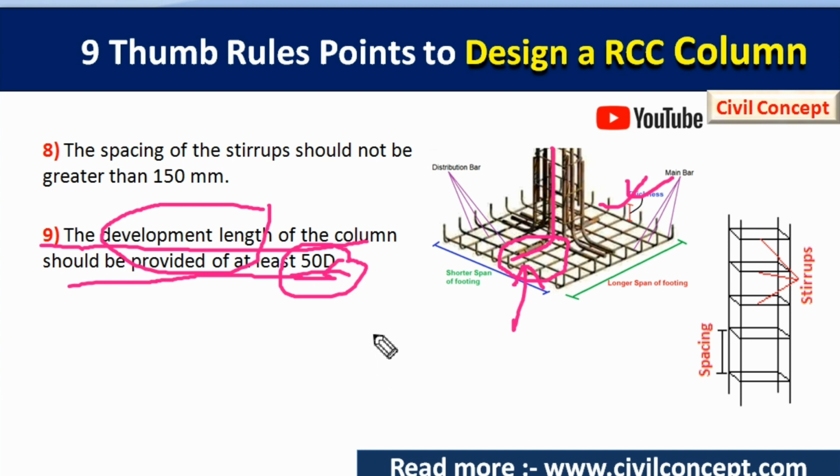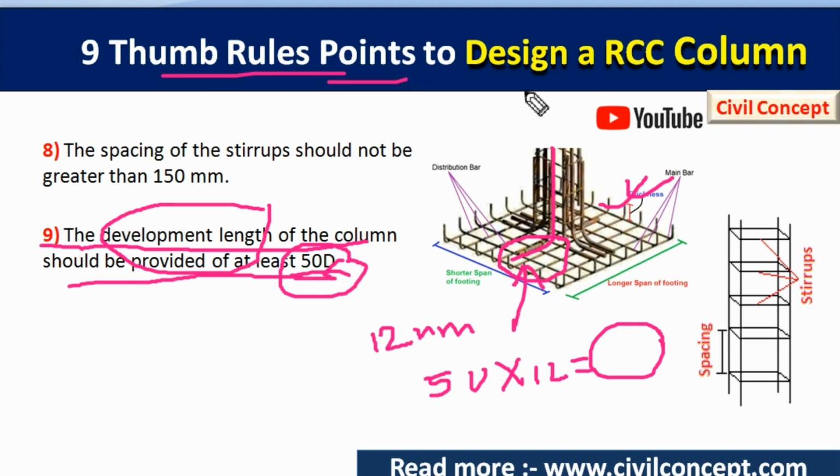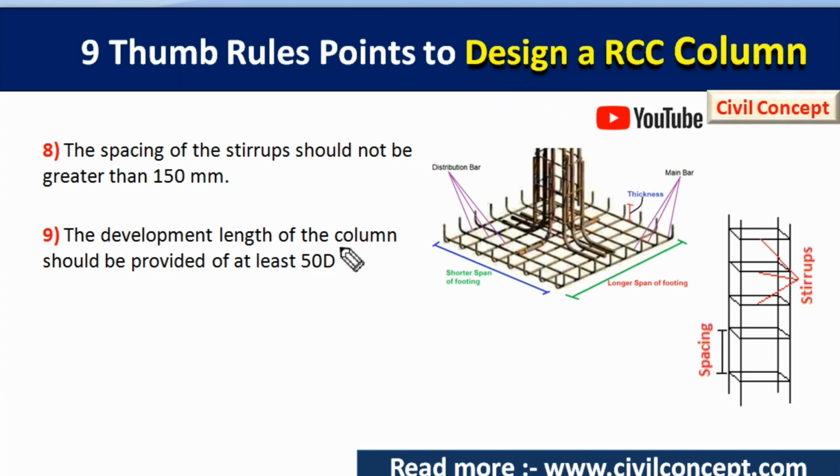For example, if we are using a rebar diameter of 12 mm, then the minimum development length should be how much? 50 into 12. And this value which comes should be the minimum development length. So guys, these are the 9 thumb rules and points which are very important for a civil engineer to design an RCC column. So this much for today.